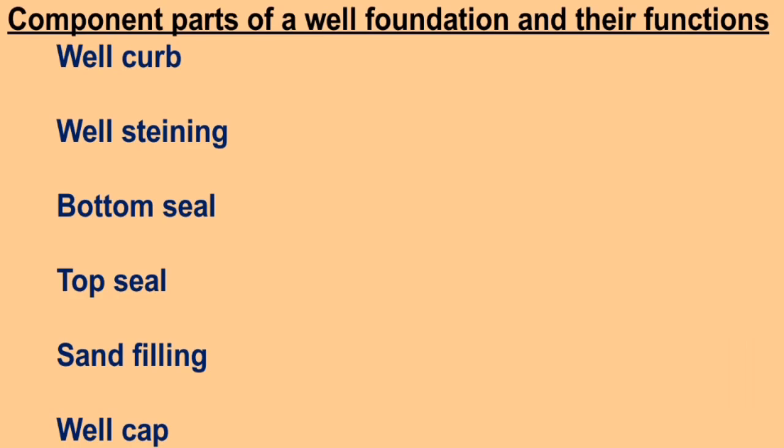The layer of concrete provided at the top of the well after filling the sand is called top seal or top plug. Fifth one, sand filling. The process of putting sand in between the bottom and top seal in the well is called sand filling. The function of sand filling is to transfer the load from the well cap to the bottom plug economically.